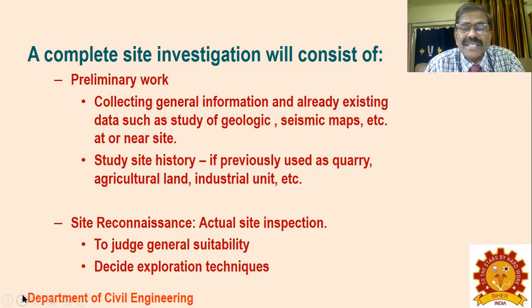Then site reconnaissance, as I said earlier: the actual site inspection to judge the general suitability and decide the exploration techniques. The site investigation will tell you, is there any water supply link? Is there any link of roadway? Link of railway? Because men and material movement is very important for any project. So all those things you will understand in the site reconnaissance itself.